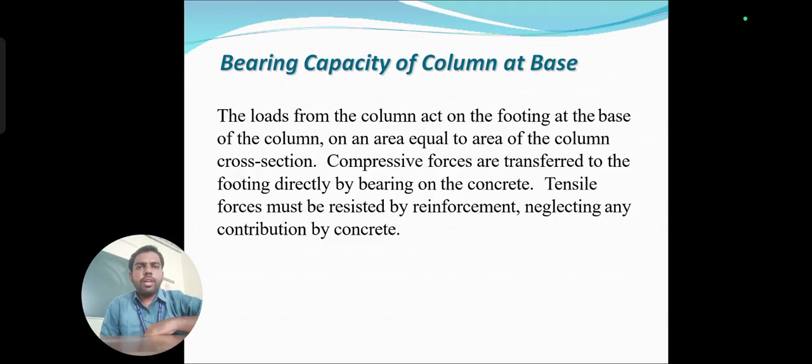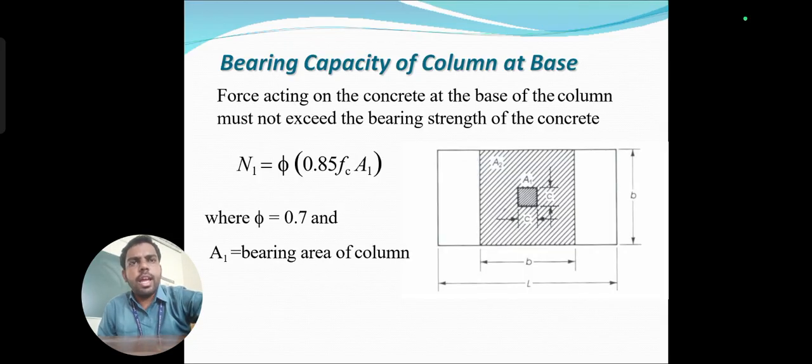We have to neglect some area also, that is, how much area should be resisted by the concrete should be minimized at that location. Why? Because it carries only compression loads, so we only have to provide reinforcement for the tensile stresses acting on that footing.